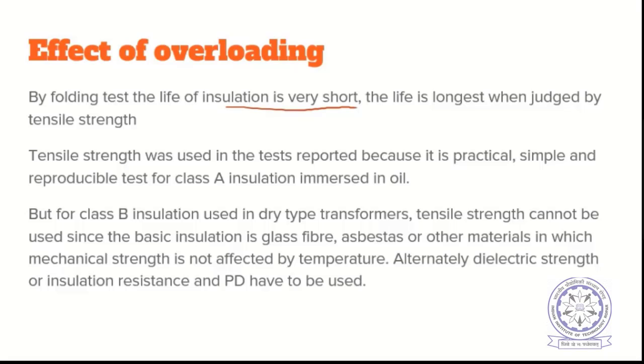So it breaks soon, and you will be estimating the life as very short, but actually it can still survive. The life is longest when judged by tensile strength test. So if you use tensile strength test, the life will be longer, and if you use just a simple folding test, the life will be shorter.